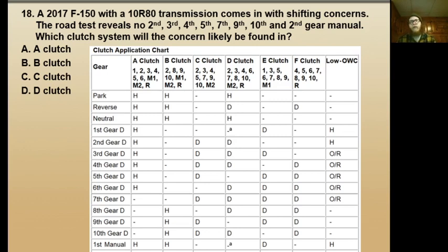Second gear manual would be, on the PRNDL, park, reverse, neutral, drive, low, one of our low gears. So sometimes you have like a manual first, manual second that you can put it into, and that would engage a one-way clutch to give us engine braking. If we're going down a steep hill, like you're headed down Mount Washington and you don't want to burn your brake pads off, then you might be going down in manual first or second, letting engine braking take over, so that just the compression inside the internal combustion engine will slow us down a little bit.